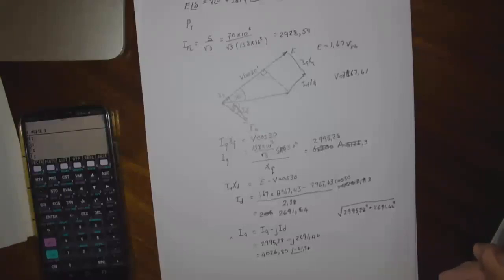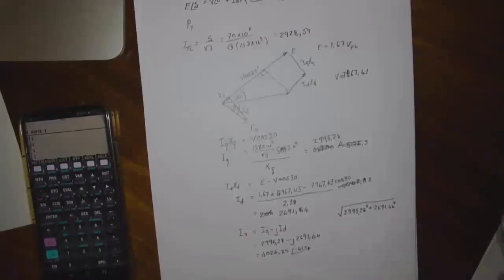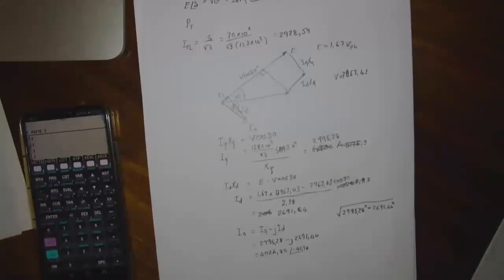Yes, I want us to use this one to get the power factor. But you don't have phi. So you have ID, you have IA, you have load angle, which means you can get the power factor.